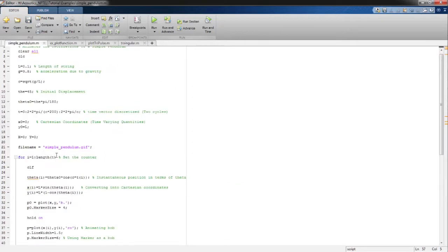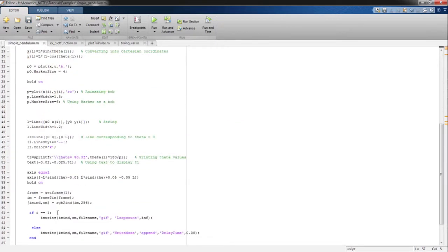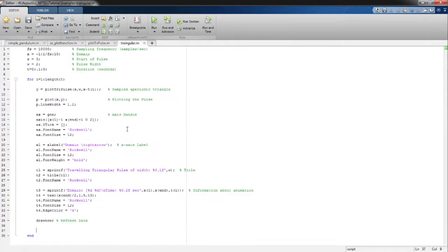We have seen how to save animation as a GIF. We know what are the important factors that should be considered while doing an animation in MATLAB. Keep that guideline in mind when you do the coding. Don't forget simple things like axis limits, clear figure, hold on.